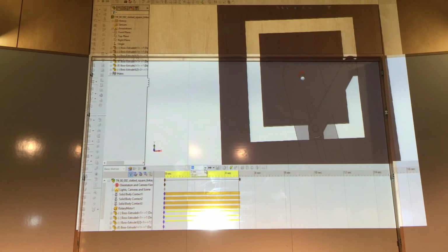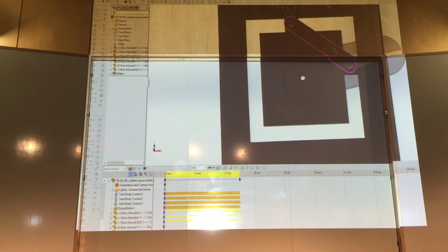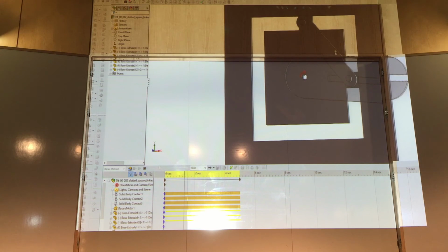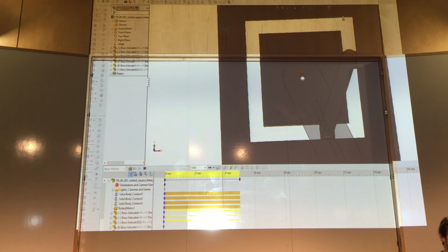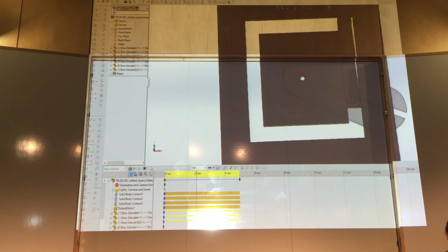Yeah, so what's fun is that it actually keeps track of the track that is moving along, and it's doing actual physical dynamics that try to prevent collisions and prevent passing through a material. So you can really start to work out different motion paths with your mechanism. And like I had talked about before, if you came from my other SolidWorks talk, I do everything as a master model initially, and then lay it out, and then I'll build an assembly if I want to do these kinds of analyses.